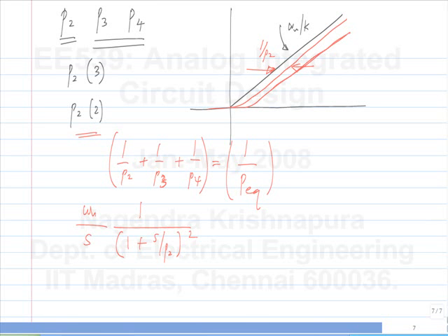Okay. So that you can use sometimes while making an amplifier. But in general, having additional poles is not a good thing, and you should definitely keep them beyond the unity gain frequency. Okay. So the whole business of frequency compensation is about keeping the additional poles beyond the unity gain frequency. So from this we can roughly take away a guide that all the poles should be, let's say, 2 times or 3 times beyond the unity gain frequency.